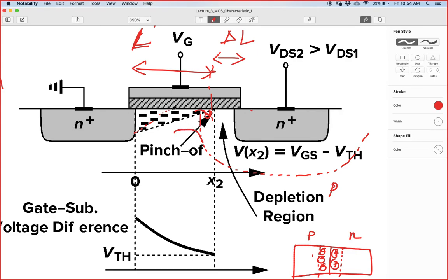And as soon as the electron crosses this depletion layer, the large potential sweeps it away. This is quite similar to the operation of the BJT. In a BJT, whenever the electron crosses from emitter to the base, because of the large potential of the collector, the carriers are swept away, right? If you remember the working principle of the BJT, similar kind of stuff happens here.